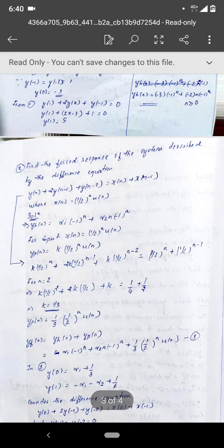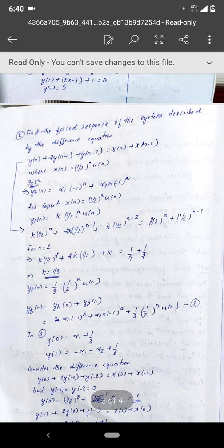Okay, so here initial conditions are absent and you are considering only the response due to the actual input. Here again the homogeneous function remained the same, because even for finding the complementary function, we tried a solution and equated everything to 0, and so we will get the homogeneous function, because input was taken as 0 for finding the complementary function also. So here also the homogeneous function will remain the same.